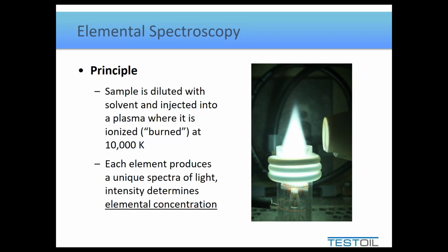Now, the correlation between each of the elements can help confirm to us if it is an alloy, in which case all those wear elements would be proportional, or if it is perhaps a coating or a layer, in which case these elements will not be proportional to each other.